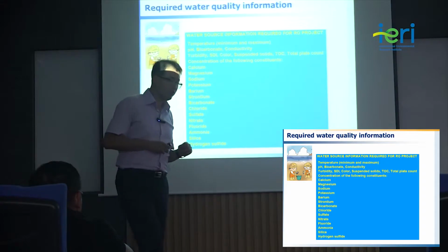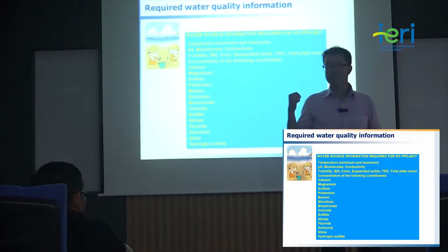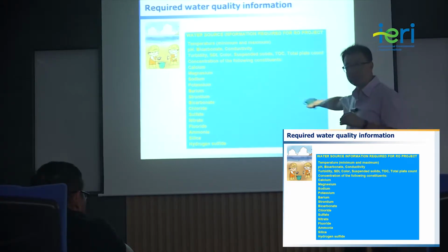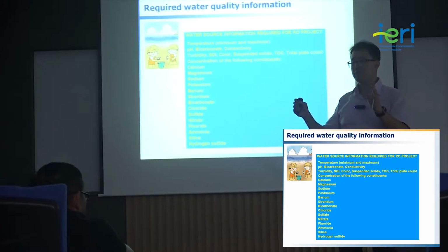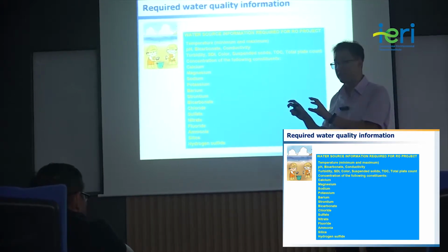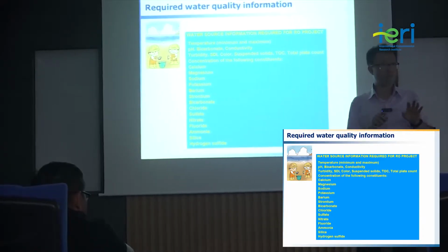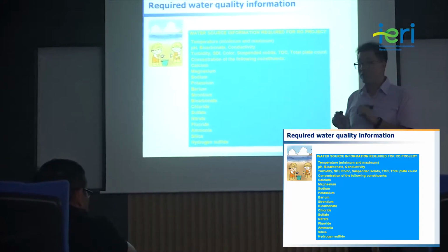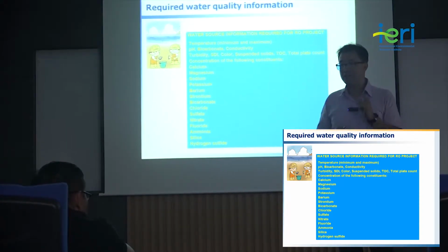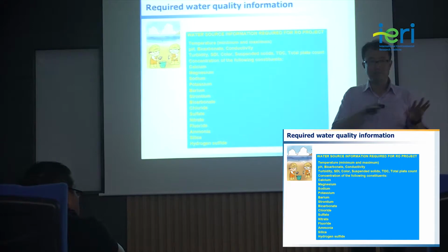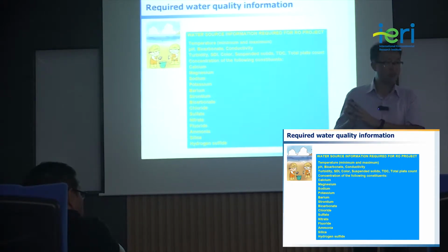So when you design membrane-based desalination, the variety occurs in the pretreatment system. Reverse osmosis is a very, how can I say, fixed design. You cannot change the configuration very much, because the one thing you can select is the membrane manufacturer. You don't need to change a lot of things when you design the membrane stage for seawater. But pretreatment has a lot of variety.